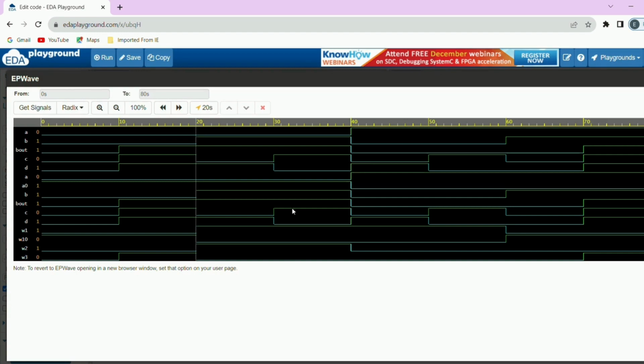We will check for another one. Here we are getting input as 1, 0, 0. For input 1, 0, 0, difference should be 1 and borrow should be 0. So we got that. But without just relying on this line, we should know how to do it ourselves.